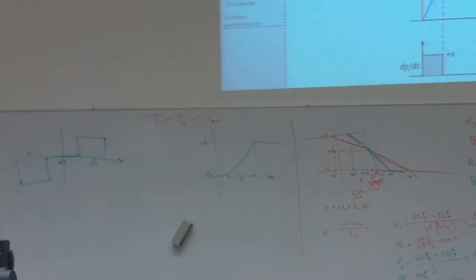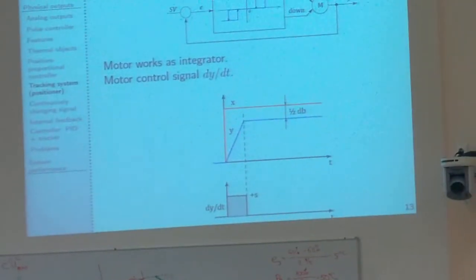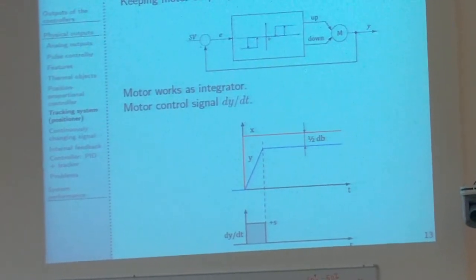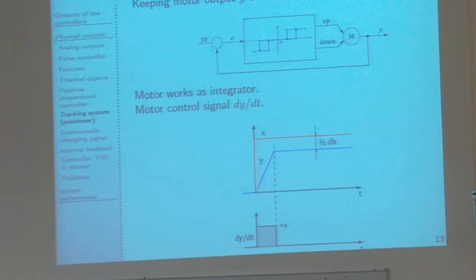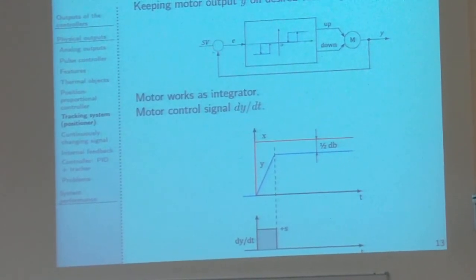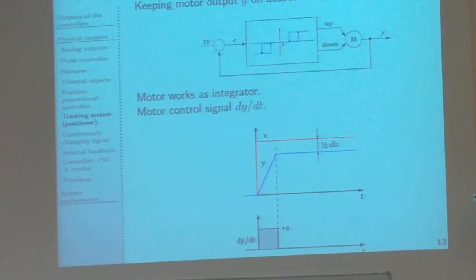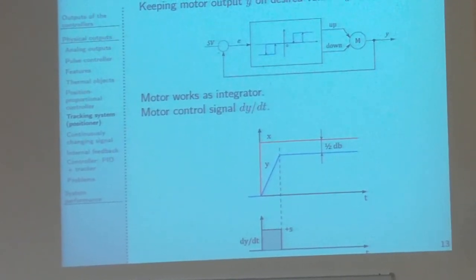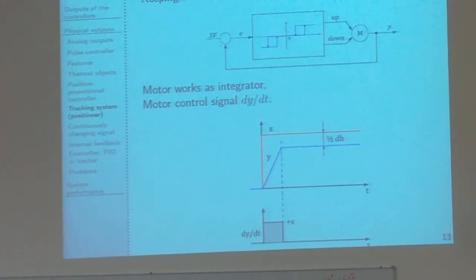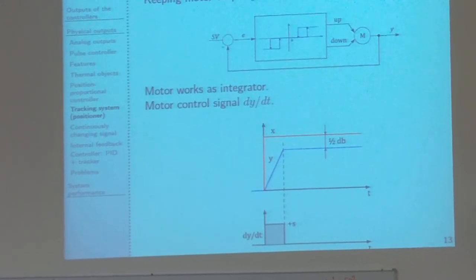So you can say, if we have such an error, it's good when the deadband is very small. In one case, yes, but on the other hand, if the deadband is very small, we can have a situation where our motor starts to rotate from one direction to another very fast, and it will be broken very soon.